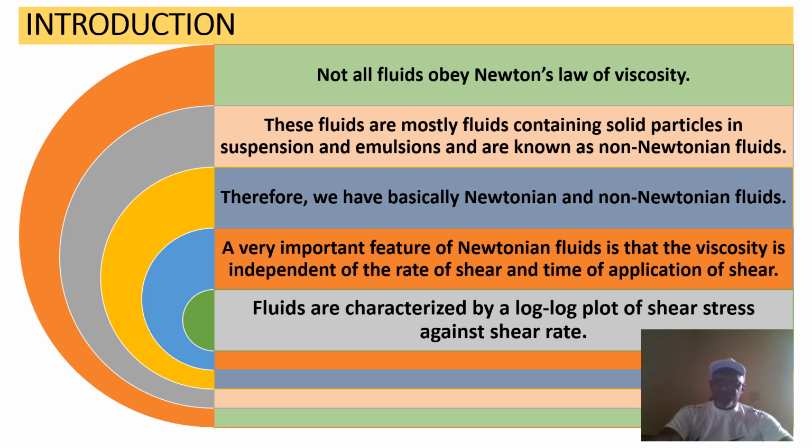Like we said, Newtonian fluids obey Newton's law of viscosity. That is, shear rate is directly proportional to the shear stress. A very important feature of Newtonian fluids is that the viscosity is independent of rate of shear and time of application of shear. Fluids are characterized by a log-log plot of shear stress against shear rate.